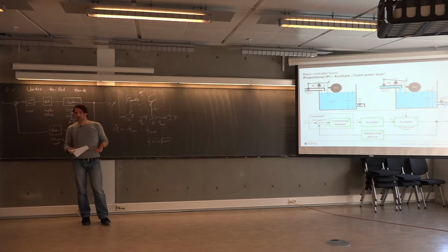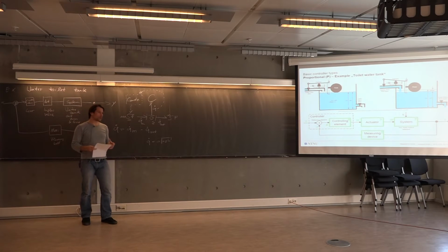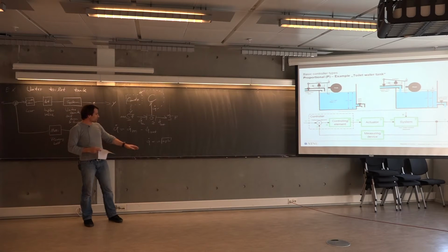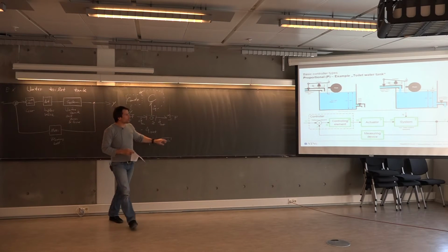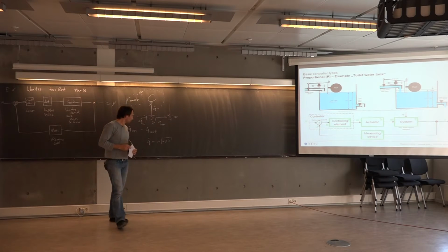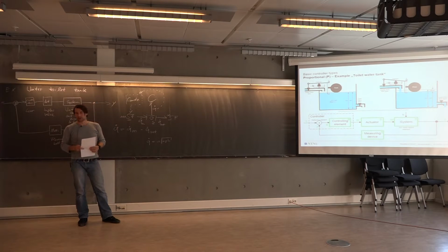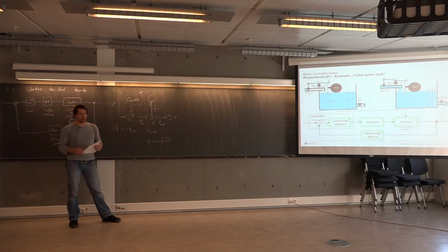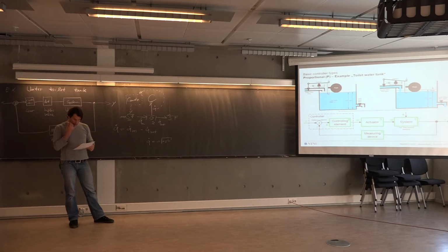Use Torricelli's law, which you can derive in fluid dynamics using the Bernoulli equation and then related to the cross-sectional area of the small little outlet where the outflow takes place, and g as the gravitational constant, and the height of the water at 0, for instance, at t equal to 0. That gives a physical reasonable value for that outflow when you press the button and flush the toilet.